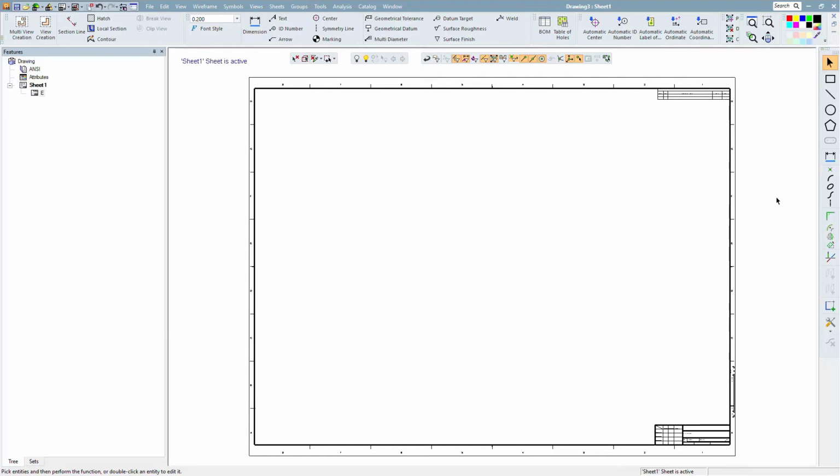On the right-hand side of the screen are the tools for drawing wireframe. Any Cimatron user will recognize these as the same functions that are found in the sketcher. And that's what they are. But really, you should rarely need to use these. Like I said earlier, drafting is for documenting the parts you've already modeled, not to draw new things. And that's the basic layout of the drafting environment, so let's get into creating some views.